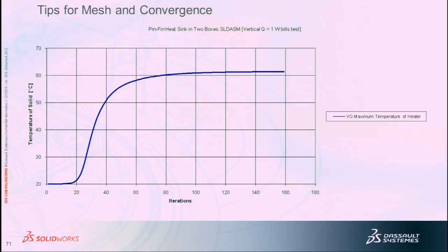It depends on the velocity, how much drag is on the vehicle, and what the recirculation is behind it. But you've seen some of those. There are validation examples you saw of the cylinder with the vortex, and a couple of other external flow problems in the validation, and you can maybe gauge. But it is trial and error. You've got to run it once, see if you got good results, and then compare it.